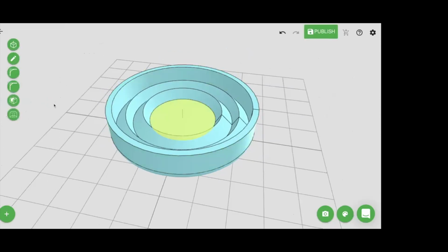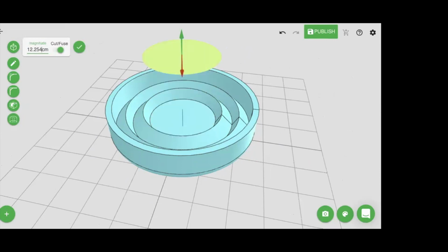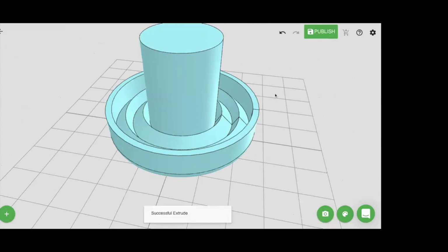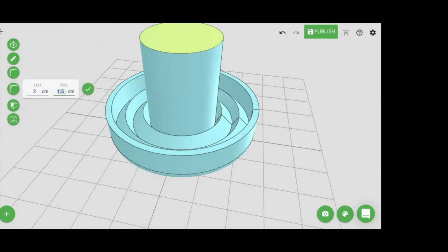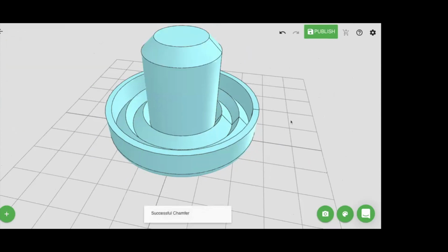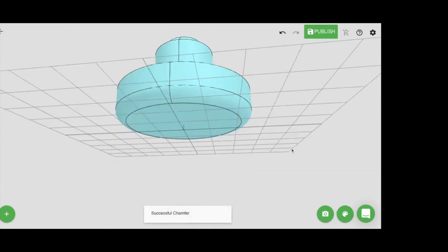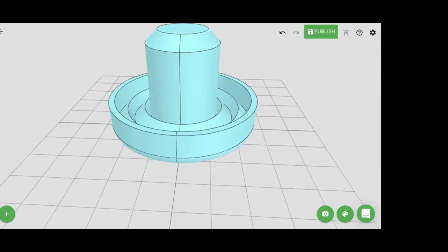If I wanted to just grab this face, and because I made it horizontal and it's totally flat, I actually have the option. I could extrude this face. So I don't even need to sketch anything. I could just grab it and kind of modify it. We'll pull it up, I don't know, 5 inches, 6 inches, who knows. I'm just freestyling at this point. So there we have it, apart, and let's just, for fun, flatten those edges again. Here we go, just to make it flat. Boom. So I have no idea what this is, but it's a thing.